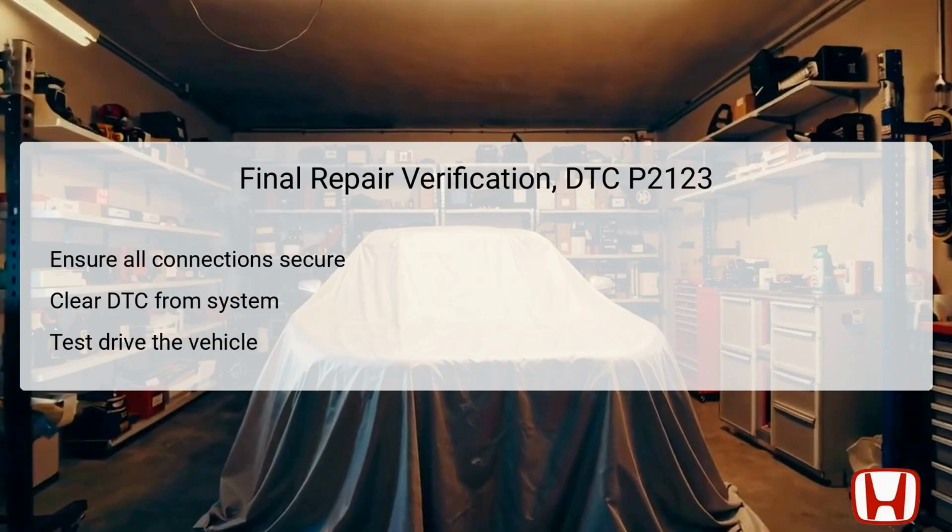Once all troubleshooting and necessary repairs have been conducted for DTC P2123, it's essential to perform a final verification to ensure that the issues have been resolved. Begin by ensuring that all connections, particularly those involved with the APP sensor and ECM, are secure and free of corrosion. After everything is double-checked, clear the DTC from the system using the HDS to reset the engine management light.